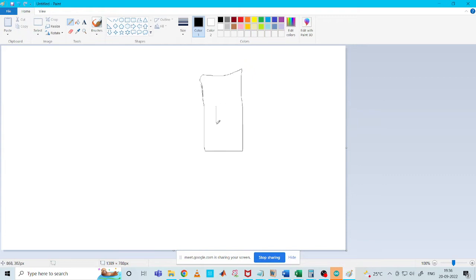Let's say this is your ADC. Here you have from 0 to 5 volts, and this gives out 16 bits. You know the resolution, right? 0 will be denoted by 0x0000 in hex, and 5 will be represented by 0xFFFF. Correct?